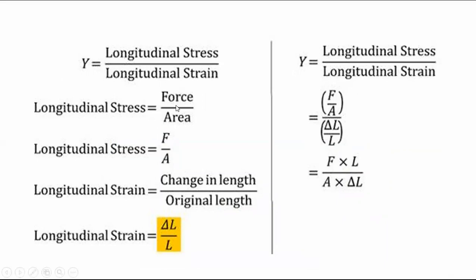We were discussing longitudinal stress by longitudinal strain. That is Young's modulus. We have calculated earlier what is longitudinal stress: resistive force divided by area, F by A, and longitudinal strain is the change in length divided by original length due to the application of external force.